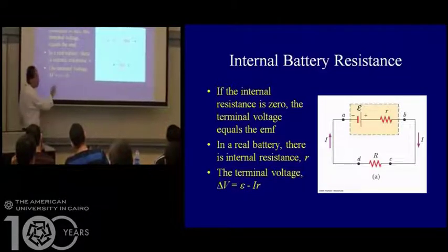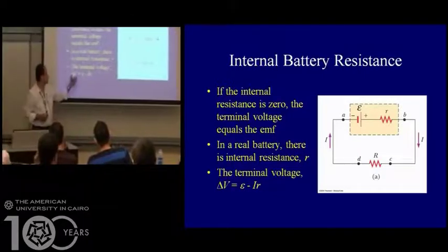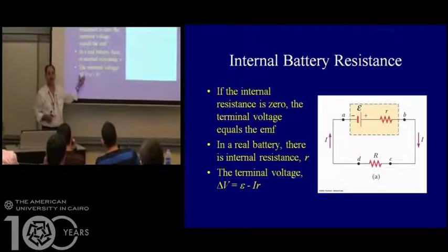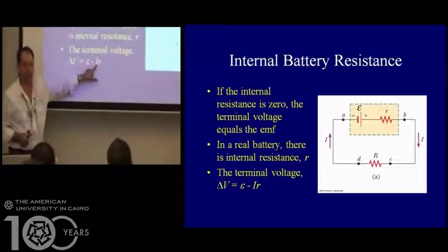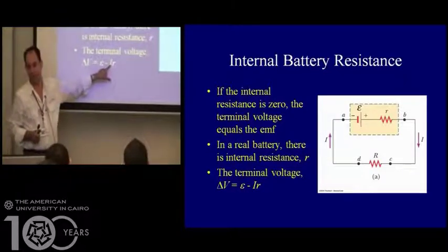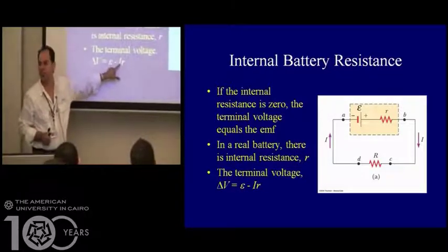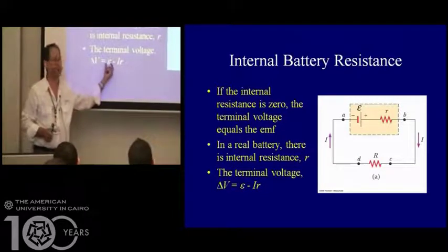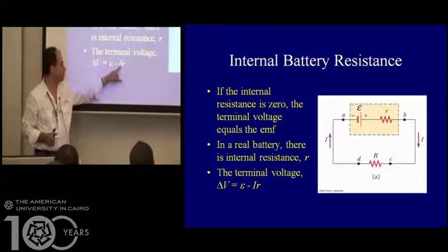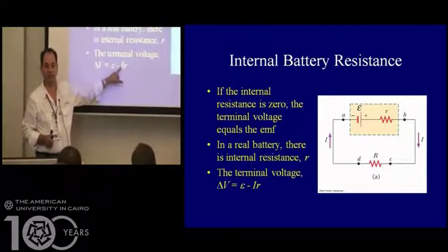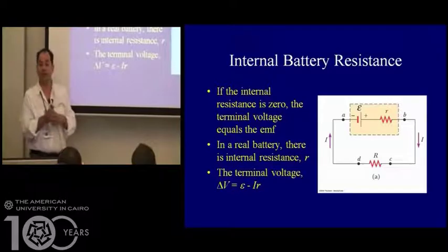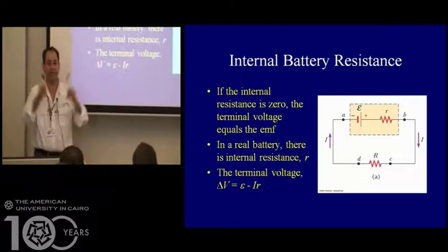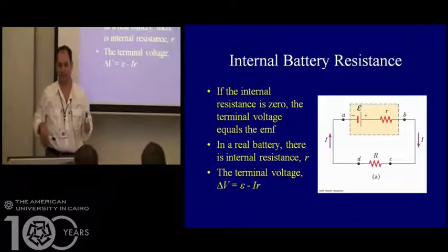If you look at that equation, the potential that you can get from any battery depends on the current that you can draw from that battery. If you draw zero current, then the potential difference will equal the electromotive force. If you increase the amount of current that you draw from the battery, then the maximum potential that you can draw from the battery will get less and less.